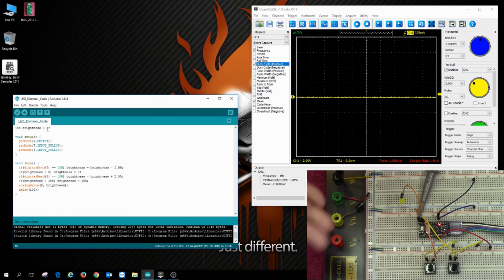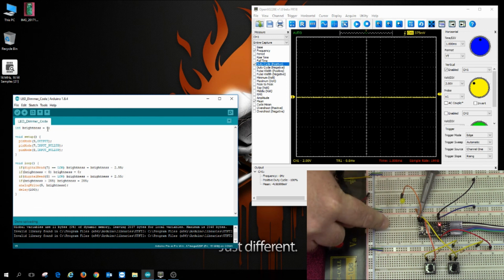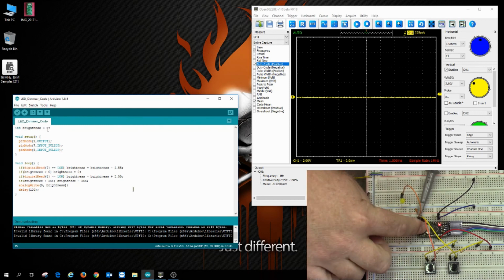And that's pretty much the basis behind using PWM to control levels. Now the output that you're feeding into this LED over here, you would basically feed into a logic level gate of a logic level MOSFET, and you'll be able to control much higher voltage applications than you would be able to do with the Arduino directly.